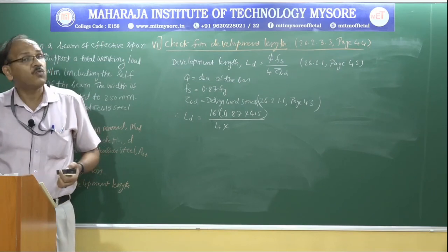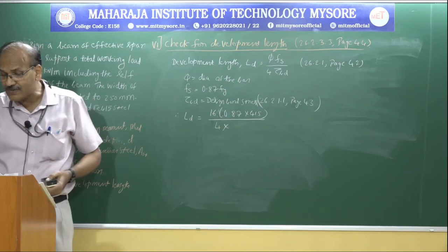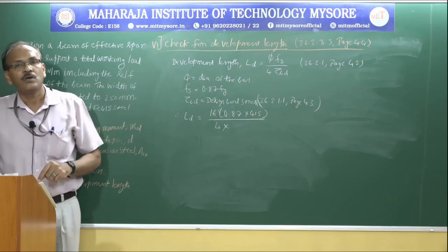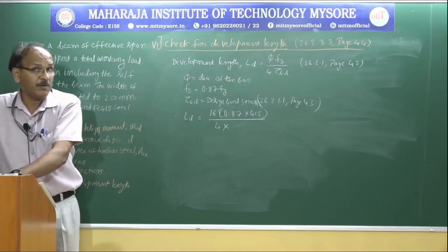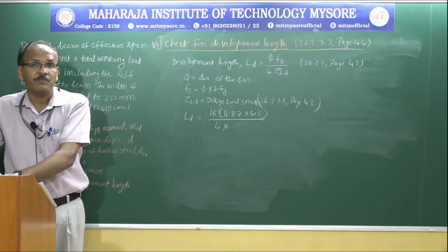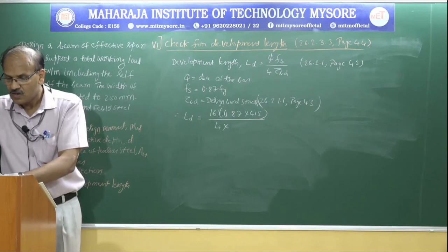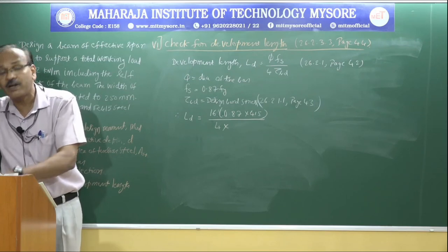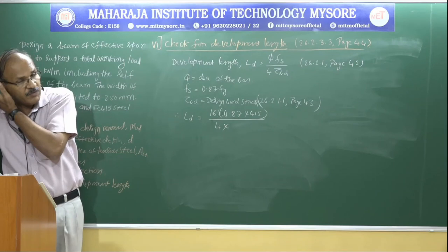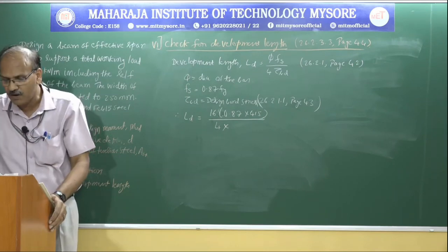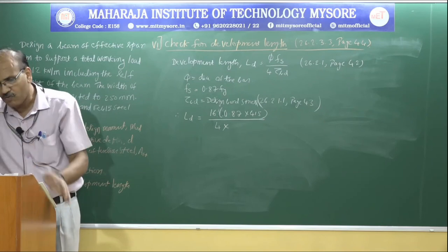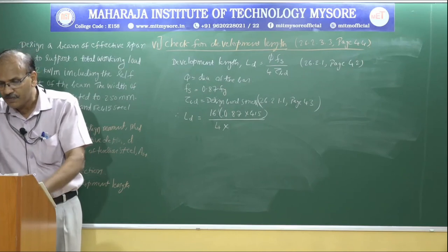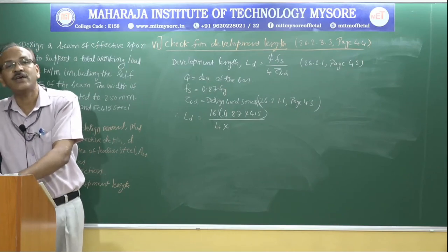If you go above that table and read that line, design bond stress in limit state method for plain bars in tension shall be as below. So these values given in the table are for plain bars. Ours is twisted bars. That's why if you go below the table in the first column, it says for deformed bars. That is the bars we are going to use. Fe 415 is a deformed bar. Bars conforming to IS 1786, these values shall be increased by 60%. That means for M20 concrete, tau Bd value is 1.2.